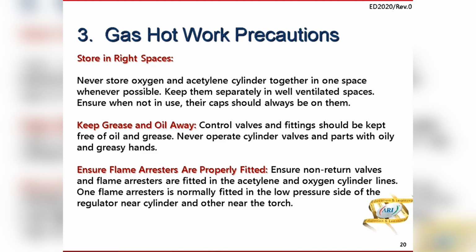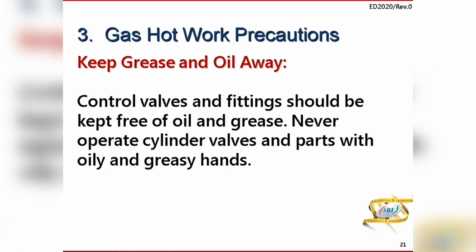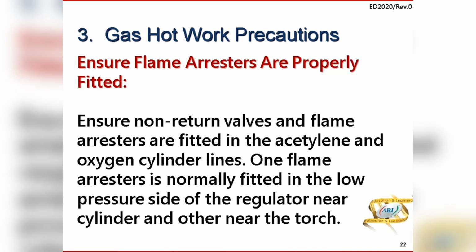Ensure flame arresters are properly fitted. Ensure that non-return valves and flame arresters are fitted in acetylene and oxygen cylinders. One flame arrestor is normally fitted in the low pressure side of regulator near the cylinder and the other near the torch. So you have to keep the grease and oil away. So the control and fitting should be free of grease and oil. And never operate cylinder valves and the parts with greasy hands.